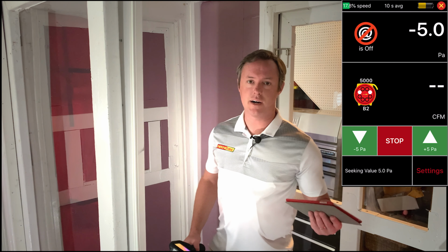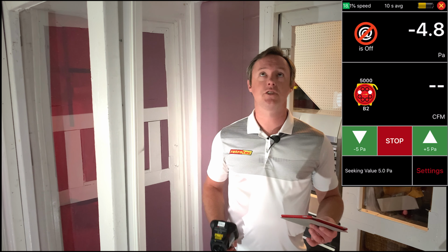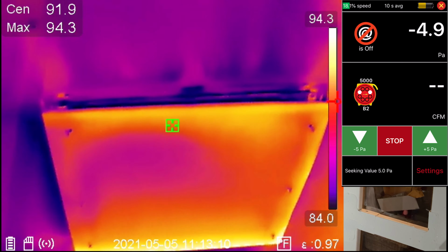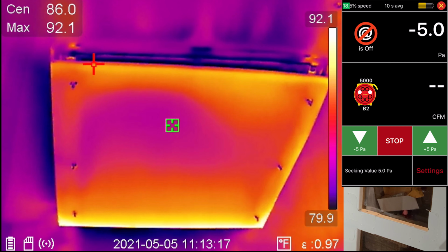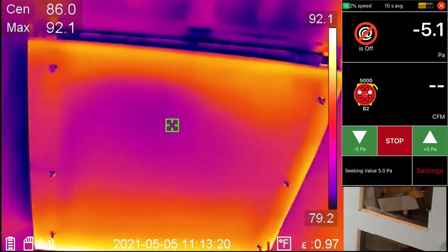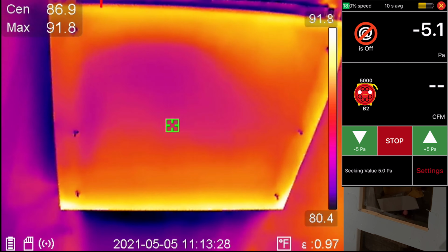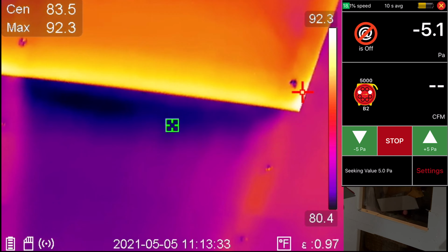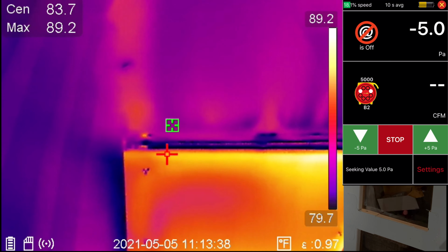We also have some panels in here that are simulating attic hatches, and I have one shut here to simulate a little bit of a leak here. And these are uninsulated, so we can see that around the edge of this it is warm, as that warm buoyant air has moved up. However, we can see some of that cool air start to come in and get in contact.